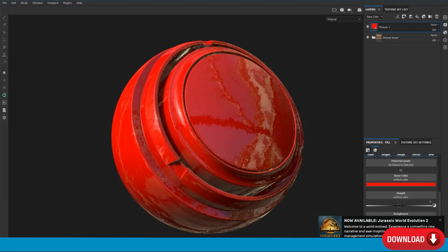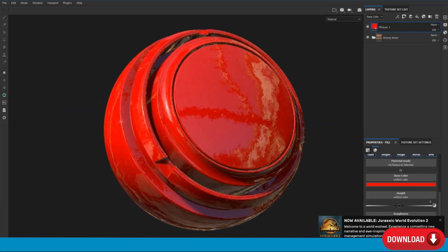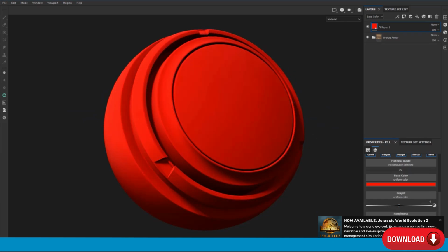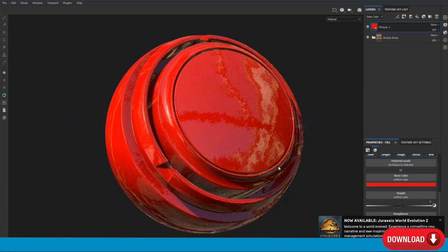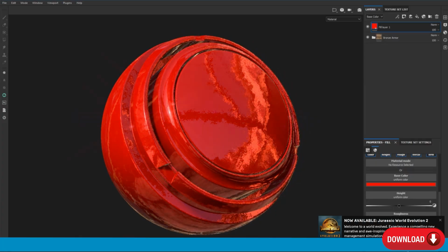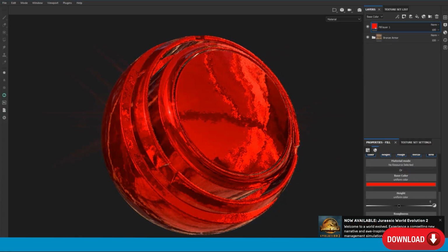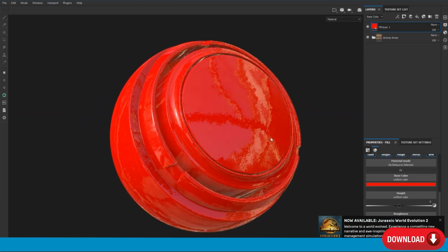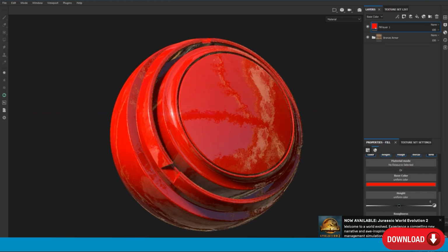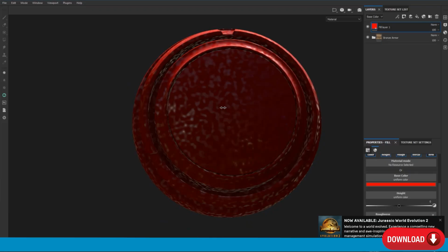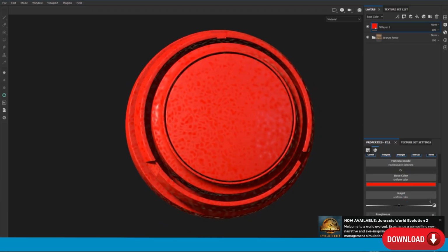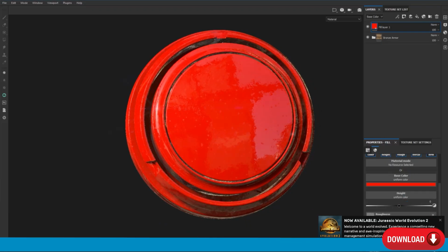I also change the roughness, being PBR. We have a range from 0 to 1, you can see here, so some values give something like a metallic effect. All these parameters are very useful to create a generic and standard material for your assets. So let's move on, and now I start with some variation in my roughness, you can see.